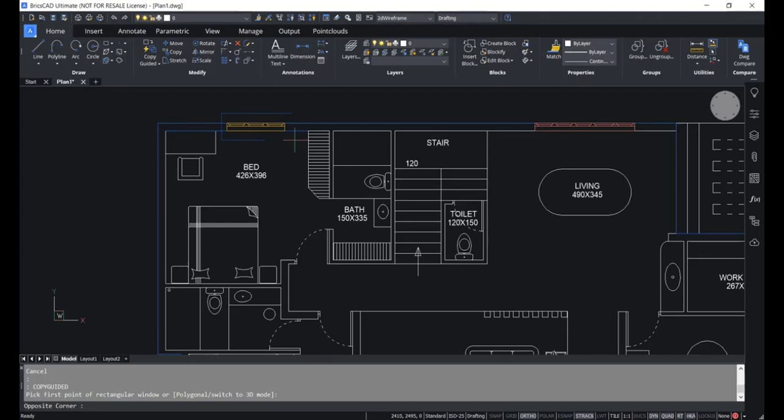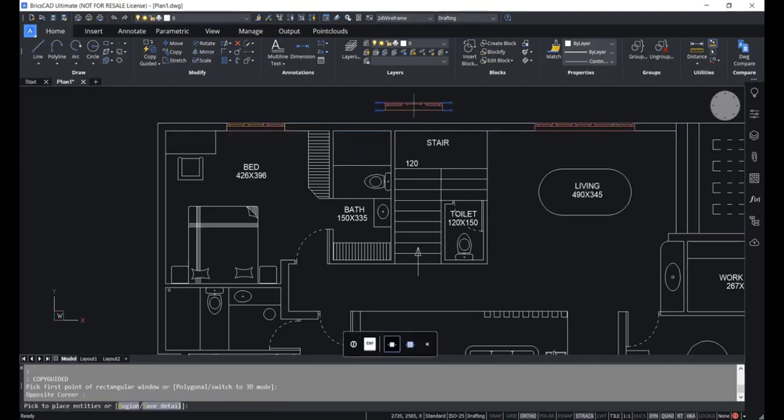And these curves will let you align this object at any desired location while taking a copy. Let's see that. I'll just pick to define the opposite corner point here. Now you can see 2 arrow marks on both sides. The blue arrows indicate the anchor points and direction of guide curves. The copied entities will only align with the geometry that matches the number of guide curves and the distance between them.